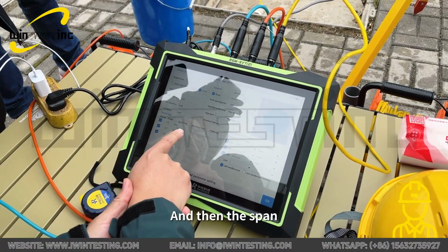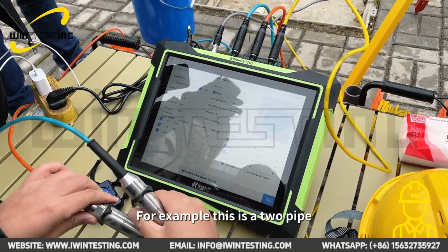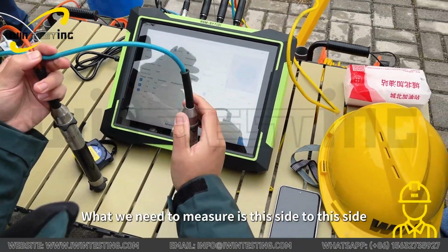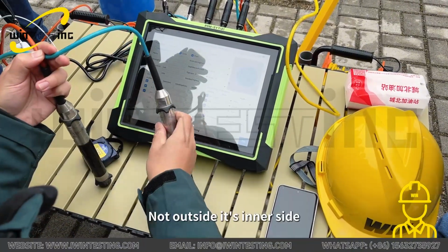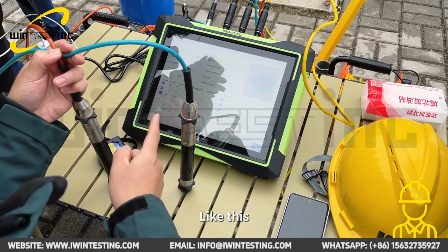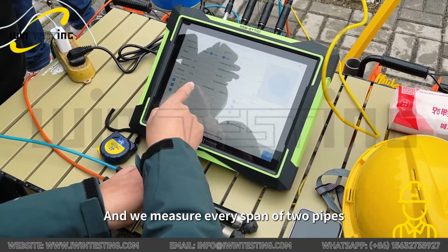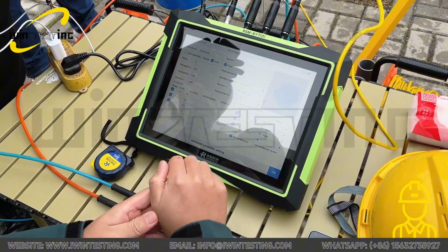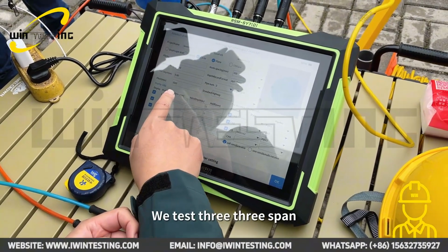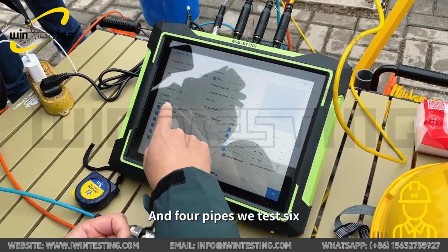And then the span is the distance between two pipes. For example, these are two pipes. What we need to measure is from this inner side to this inner side, not the outside. And we measure every span of two pipes. For a three-pipe pile, we test three spans, and for 4 pipes we test six.